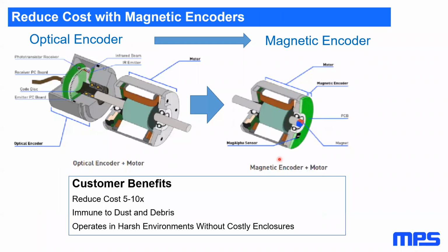Okay, so last thing I want to mention, I mentioned this at the beginning, but I was looking for a place to put this slide: why use a magnetic encoder anyways, when you could just use an optical encoder? Heck, you could find an optical encoder that's 20 bits. So then why go through all this mathematics and looking at graphs and the trade-offs between bandwidth and resolution when you could just throw an optical encoder on? And there's two main reasons. One is size, and the optical encoders, they're large.